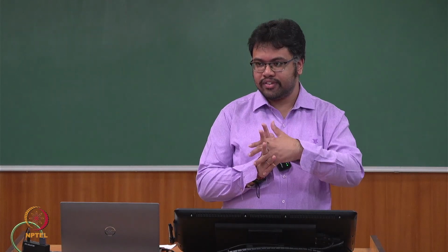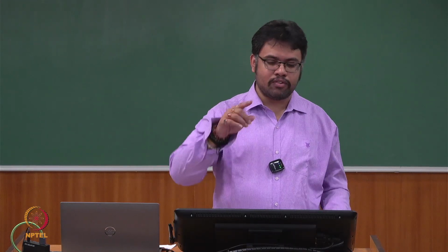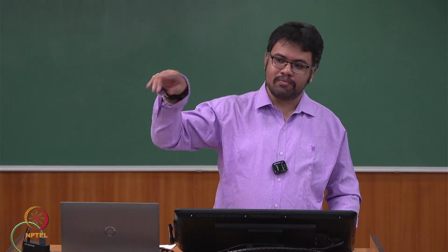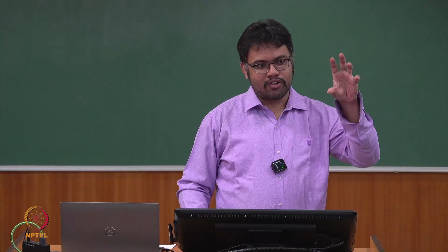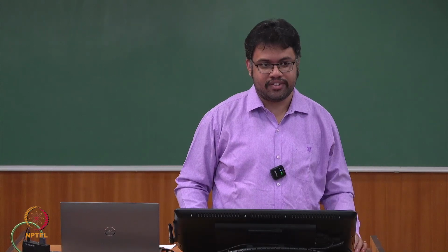Another thing is that we also estimate the capacity of the structure. From there, we try to balance it. That is known as the capacity based approach, where you plot the capacity spectrum and the demand spectrum. Once they cut at a particular point, you basically should design it.